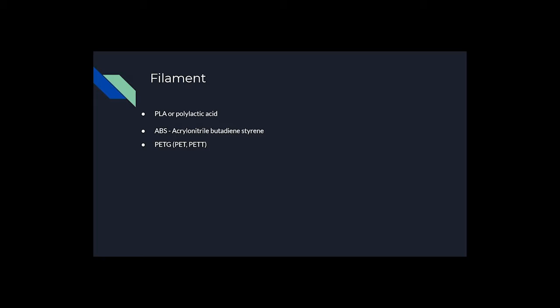PETG, PET, P-E-T-G, there's many ways to say that, but this type of filament is basically a child of PLA and ABS. You have a very strong filament, just like ABS, but you don't have such an odor when printing, and it's a lot easier to print than ABS.